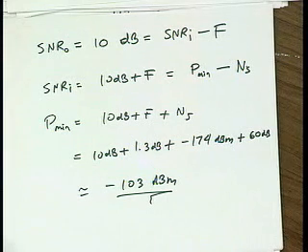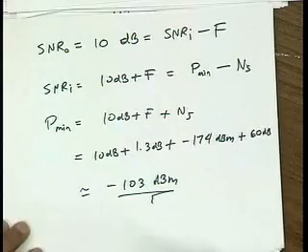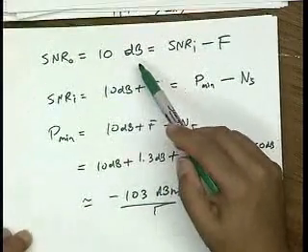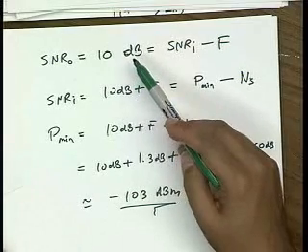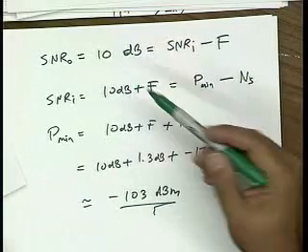Yes, Kevin? I guess this is a general question. When we have a communication system, what part of this depends on the coding or modulation scheme? The 10 dB part. You either do some calculations or you do some simulations to determine that to get a bit error rate of 10 to the minus 3, you need 10 dB SNR.